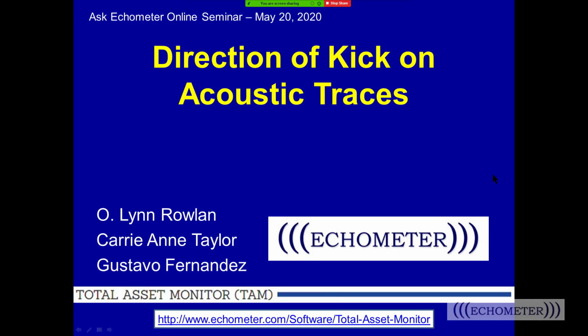And the wellbore schematic typically identifies anomalies or objects in the well that increase or decrease the cross-sectional area. Those anomalies will show up as an upkick for an increase and a downkick for a decrease in the wellbore. I'd like to thank Carrie Ann and Gustavo Fernandez for help on this presentation.